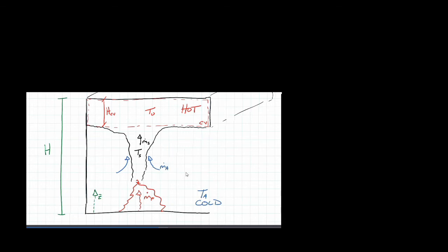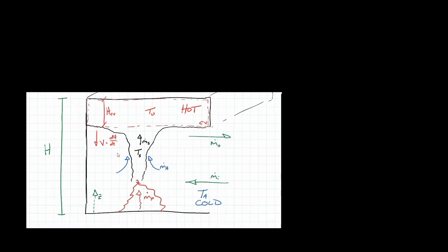So if you look at this whole system, this little itty-bitty amount of fuel, the ratio between the mass of your fuel and the mass of the smoke is about 10 to the minus 4th. So it's just this tiny addition of mass. But that little bit of mass creates this huge heat pump cycle relative to mass coming in and mass coming out, where M sub I and M sub O are basically the same. But the energy associated with that upper layer of gas is what creates that radiative effect that causes flashover.